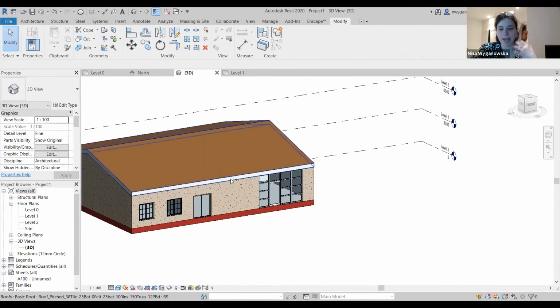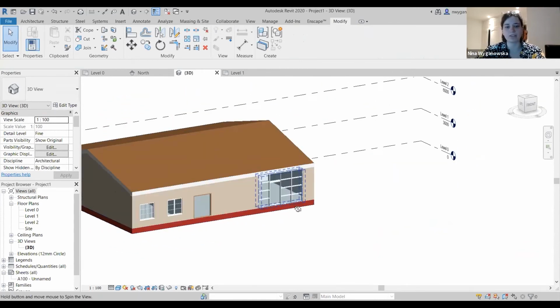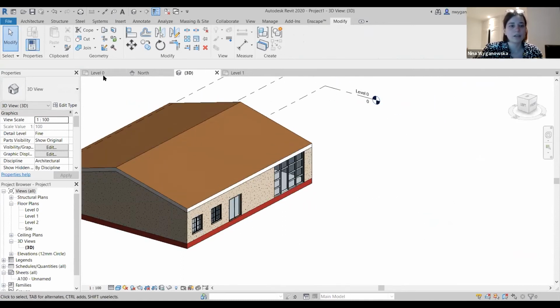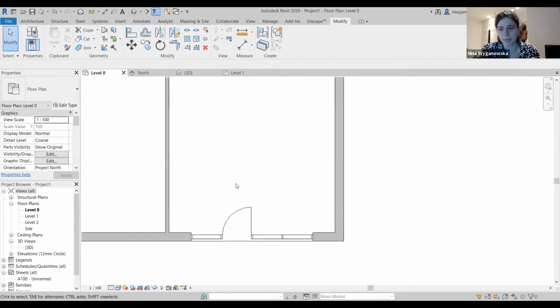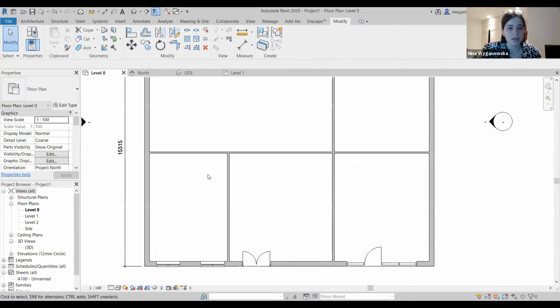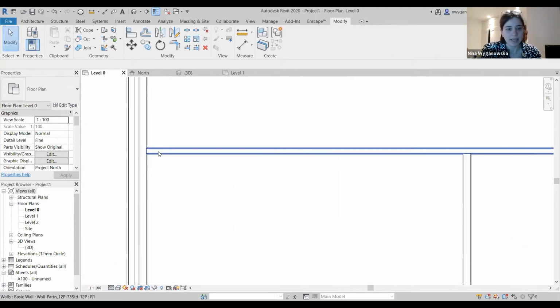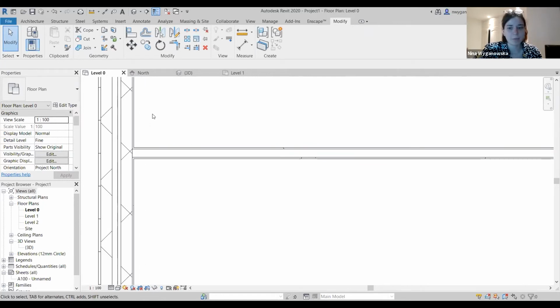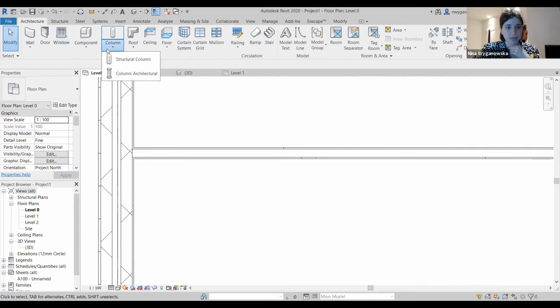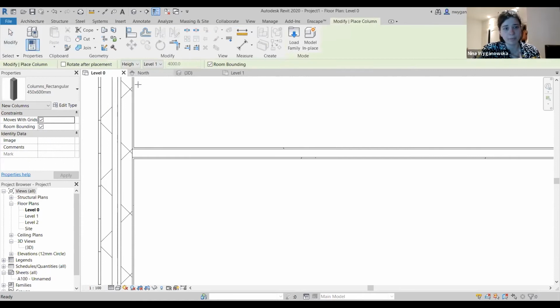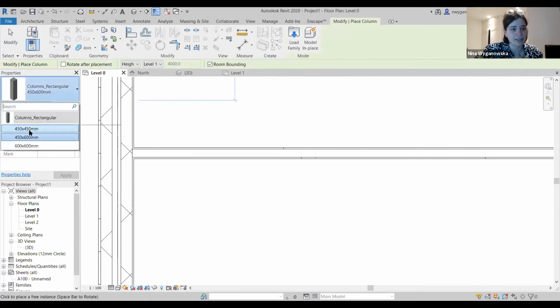But the program allows you to do a lot more things than just build basic walls and things. You can set up the structure, as I said. So let's go back to fine. If I said, for example, that I want my structural primary elements to be steel, I can go back to this and say I want a column. That automatically loads me an architectural column.